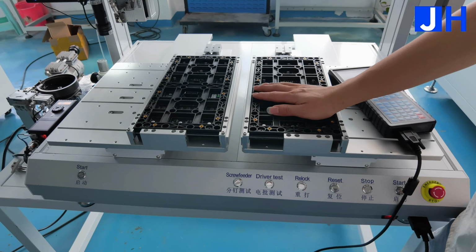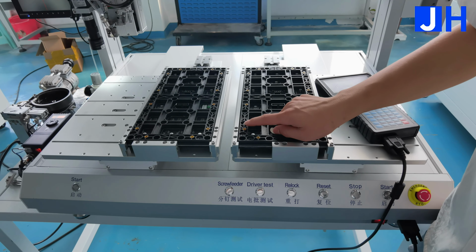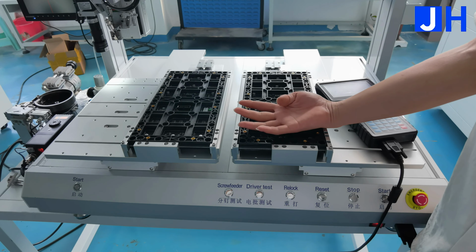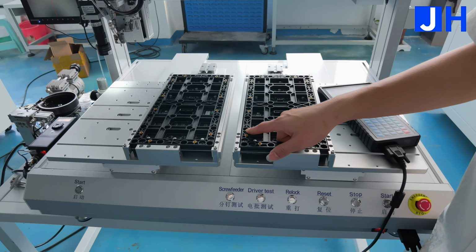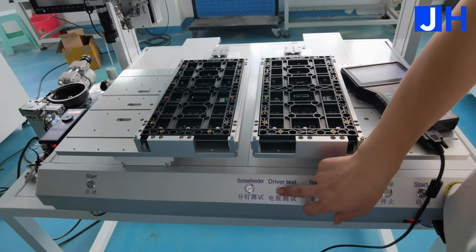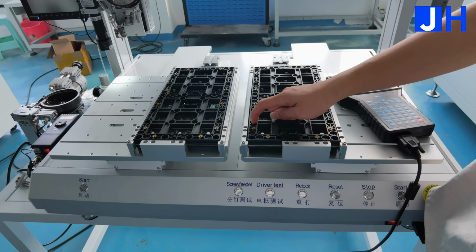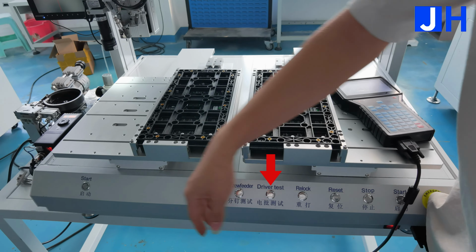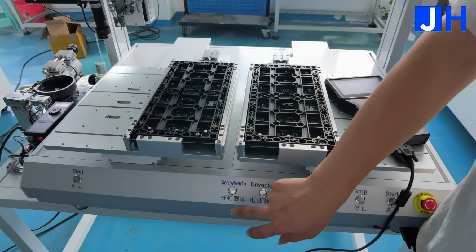If during normal operation, the machine has an alarm, such as a slipping alarm, or if there is no screw on the nozzle and it keeps running idle, the machine will also alarm. We check if there are any screws, press the nozzle to open it. If there are any screws, remove them. Then press the drive test button. The machine will insert an additional screw at the original coordinates before resuming operation.